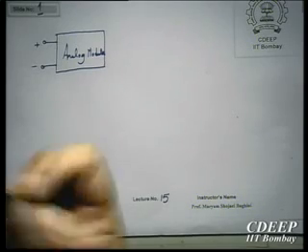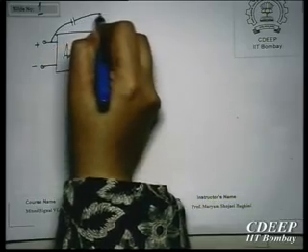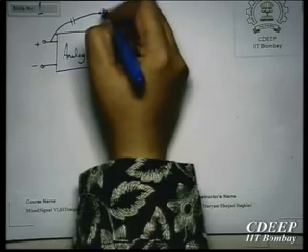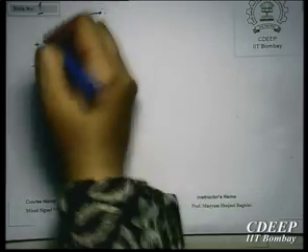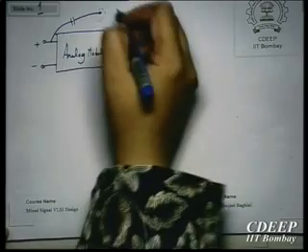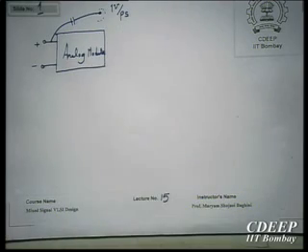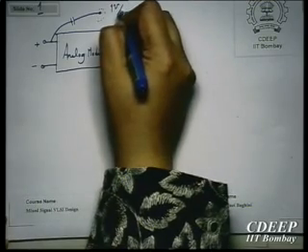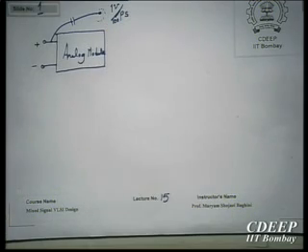Now, suppose you have some sort of coupling through some parasitic capacitance from a digital source. So there is a switching happening at this node, which is coupled to this node. And just to get an idea of what will happen, suppose the speed of switching here is 1 volt per 100 picoseconds. 1 picosecond is too fast.